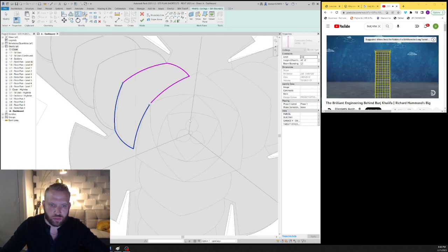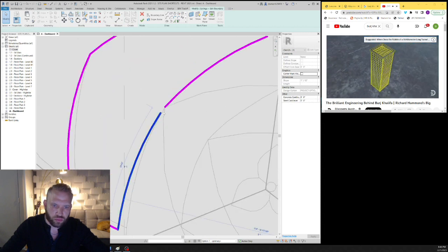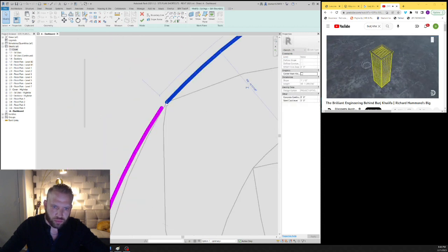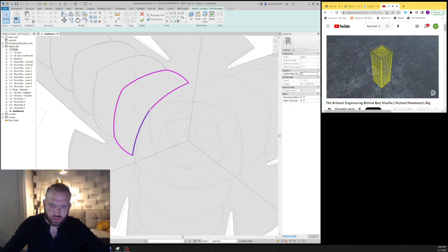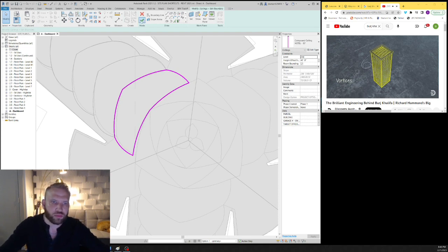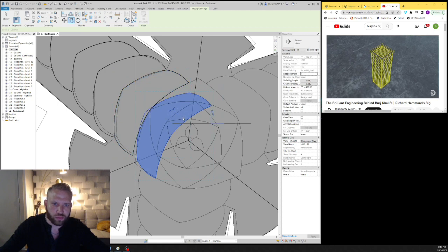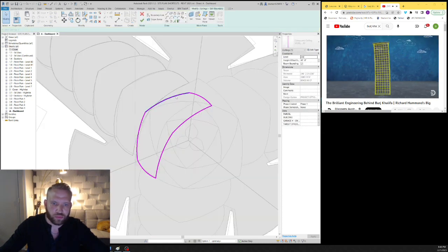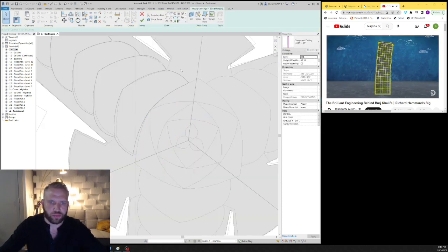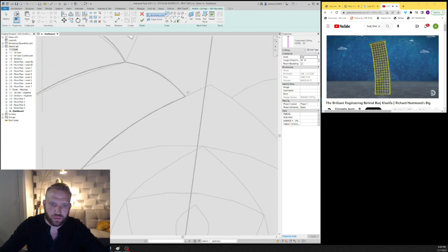And this is the tall building problem. When wind swirls around a building, it forms small whirlwinds called vortices. These alternating pockets of low air pressure create forces on the building that can cause it to rock from side to side. Not as much as this, obviously, I've exaggerated it to make a point, but you get the idea.